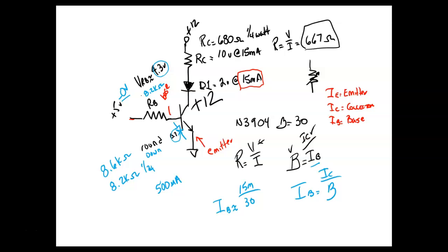So we checked it with power. You can do this in your car. So instead of pulling those fuses out, even your little tab fuses that we use now, you notice there are 2 little tips up there that you can get to with a meter, right? You understand? So you can just go through there and just measure with your meter. If it's dropping 12 volts, it means just what? If a fuse drops 12 volts, it means just what? It's blown or open, yeah.